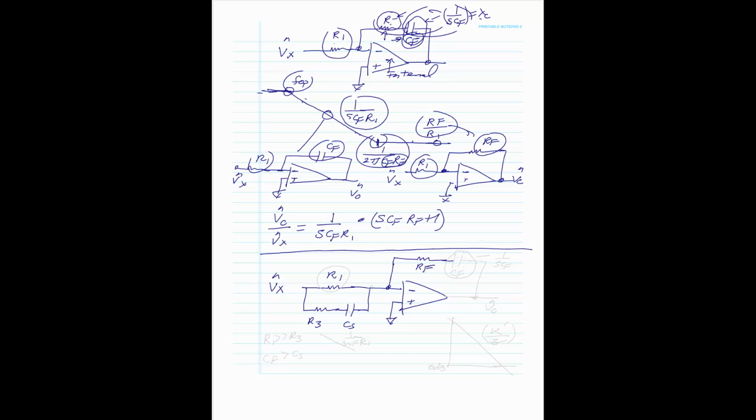And we need an integrator to be a straight line, because always in feedback we want a straight line. Ultimately, our loop gain, we always want a straight line. Again, we're getting ahead of each other, but that's okay for right now. We always want our whole system to be some k prime over some s, and k is going to be a different constant than the constant around the loop. Okay, so right away we have this system right here.